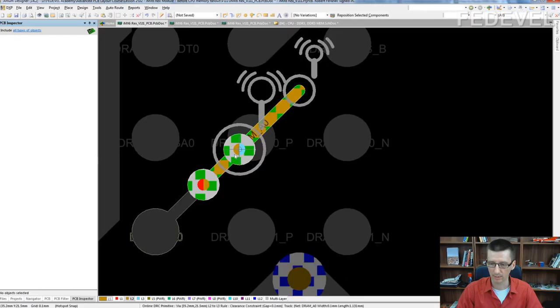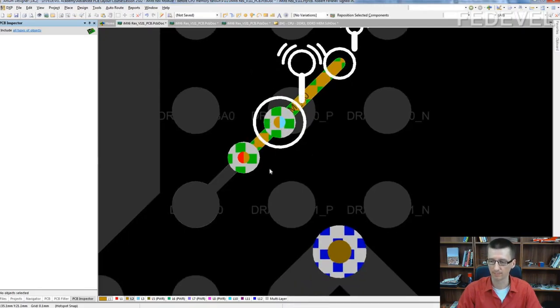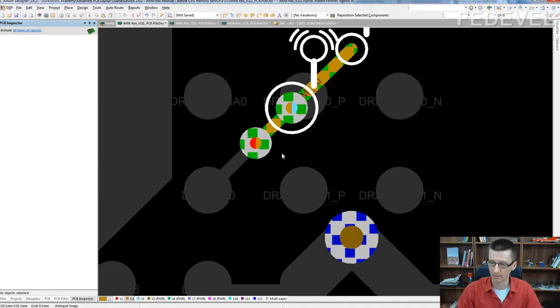Also, don't place the vias very close to each other. Again, there are some rules how close two holes can be drilled, so I just place it like this maybe. Why we don't use micro via from layer 1 to layer 3? Why we are doing it so complicated that we go from layer 1 to layer 2 and then we draw this short track and go from layer 2 to layer 3?